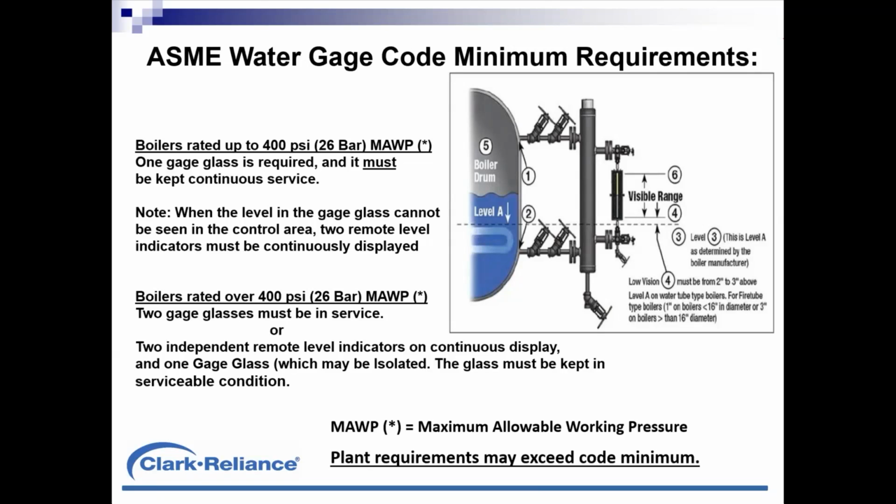If suddenly, for some reason, those 2 transmitters start deviating significantly, I have the option on my gauge glass to turn to as a referee to help me determine which indirect remote reading transmitter is reading correctly, so I don't mistakenly pick the wrong one. So keep in mind, these instruments are specified and installed for good reason.